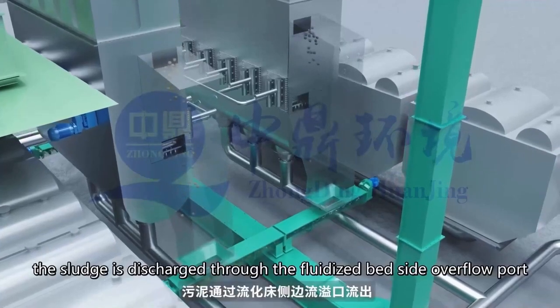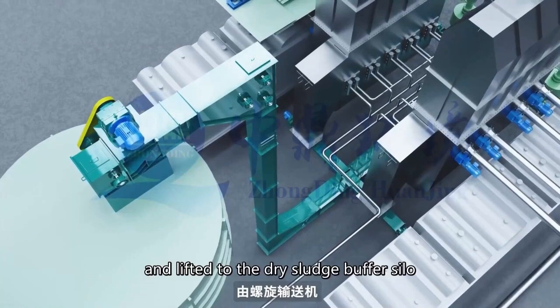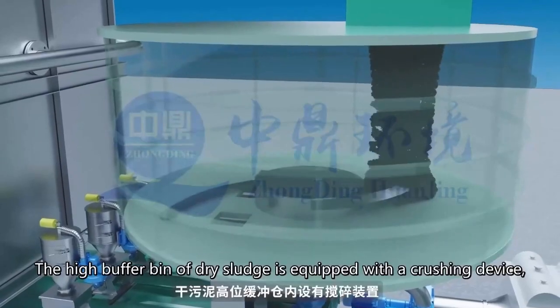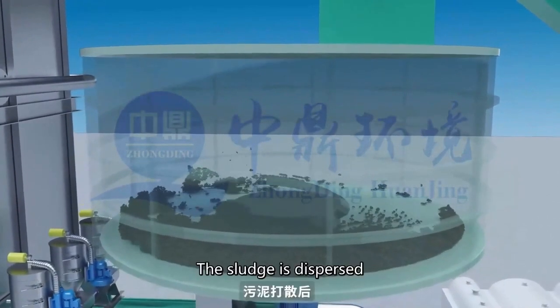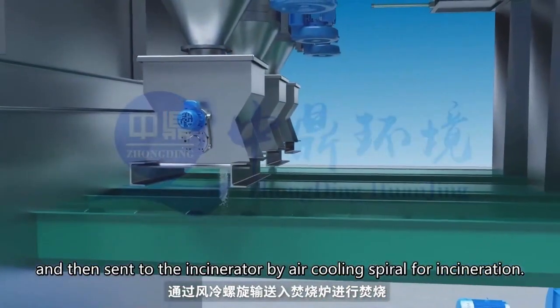After drying, the sludge flows out of the side of the fluidized bed, lifted by the screw conveyor and Z-shaped scraper to the furnace buffer compartment for dried sludge. A crushing device is placed in the high-level buffer space for dried sludge, effectively preventing rehydration and agglomeration of dried sludge. After dispersion, the sludge is transported through the screw conveyor to the incinerator for incineration.